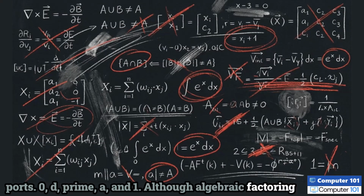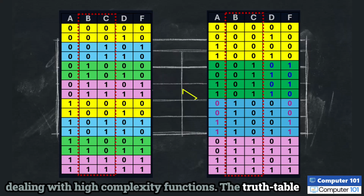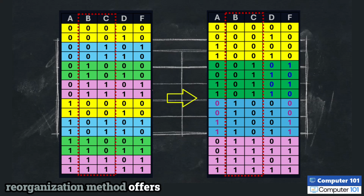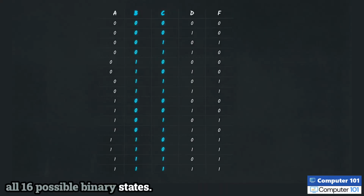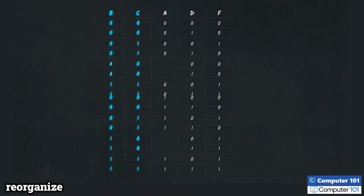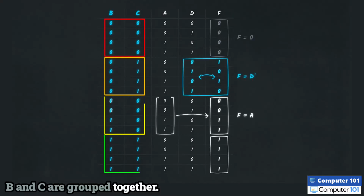Although algebraic factoring works, it is time-intensive and prone to error when dealing with high-complexity functions. The truth table reorganization method offers a more robust visual alternative to manual Boolean algebra. We start with a standard truth table for 4 variables, accounting for all 16 possible binary states. The first step is to reorganize the columns so the chosen control variables, B and C, are grouped together.